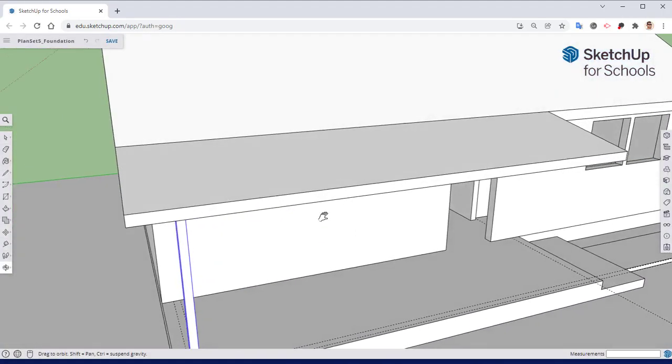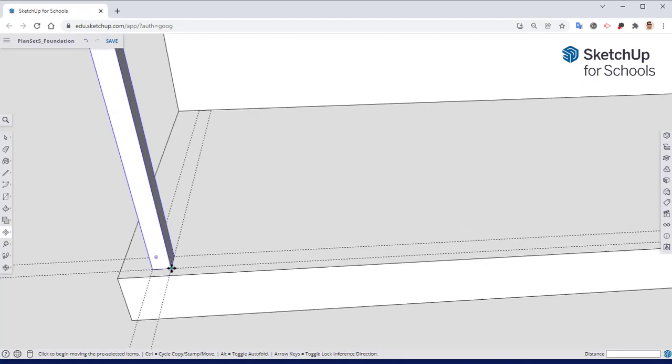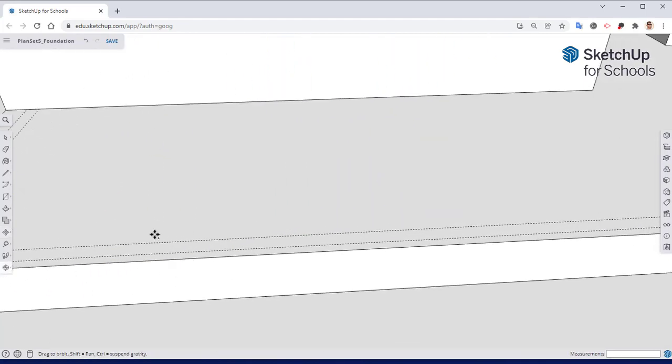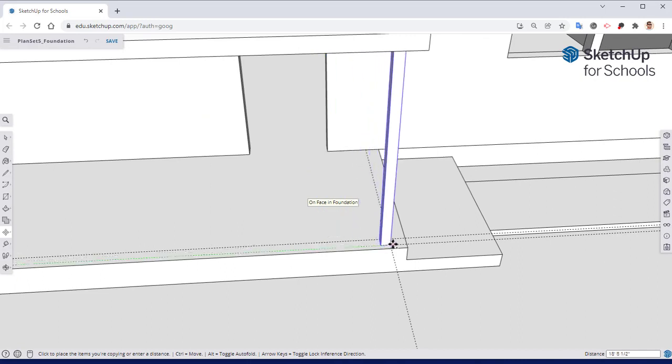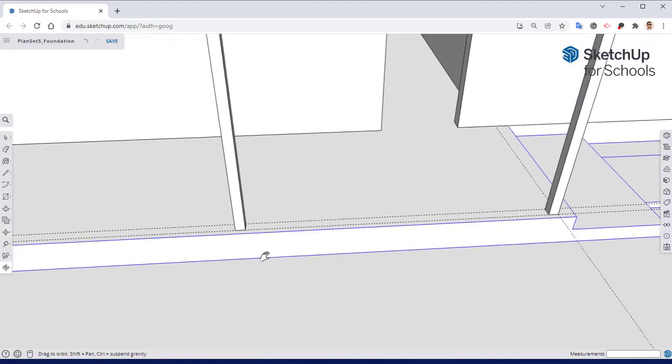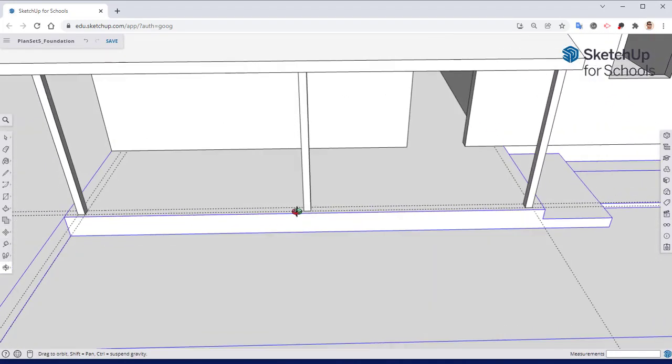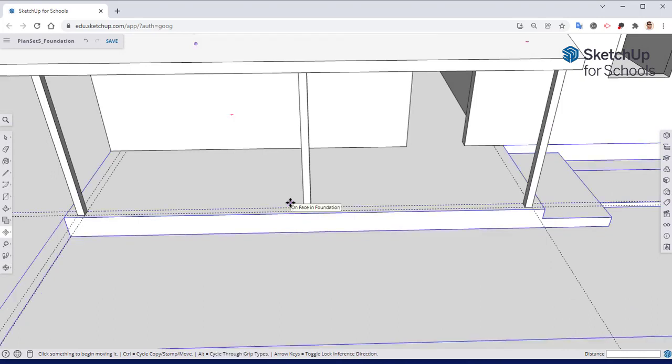Now what we're going to do is take our move tool, we're going to go to this right corner, click on it, hit Control. We're going to drag it all the way over, set it to our guide that we've already created. After you click, you're going to type in \2, enter, and that's going to create our center point as well. So if we did multiply, it would move it another one to the right. We wanted to divide this inner space, and so we put the divide key instead of the multiply key.